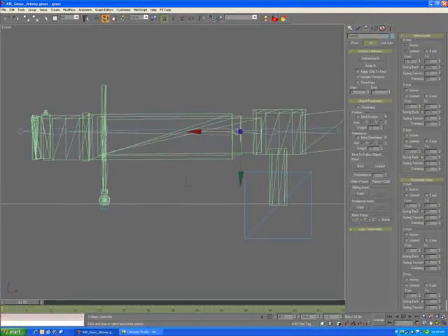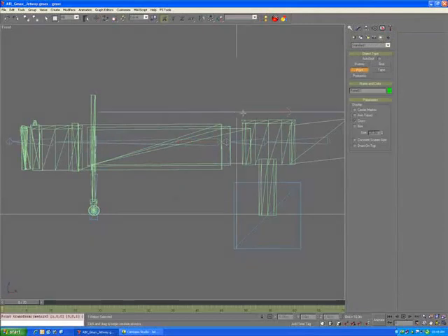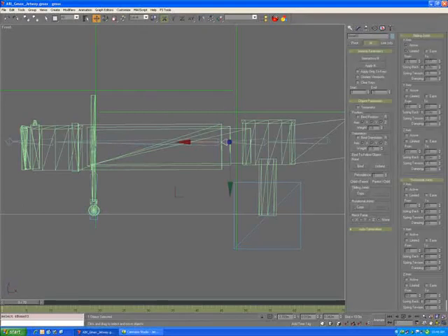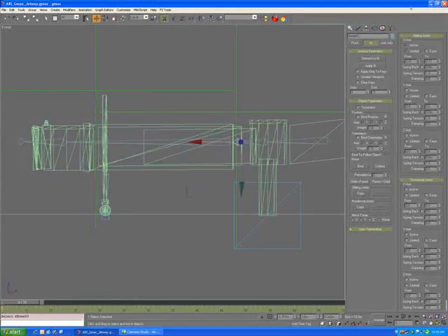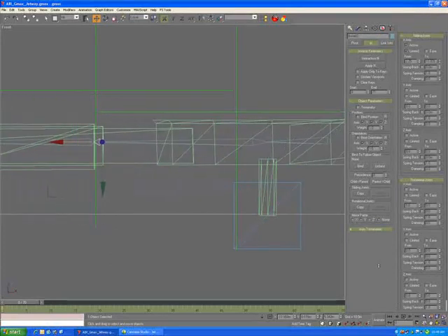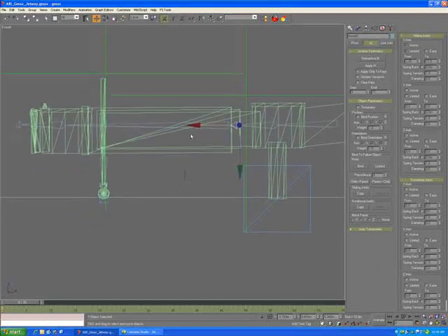So what you can do, if you want to, is put markers in. If we go in here, we can put a point in, say, there. That's the farthest, and then a point in, say, here. That's the farthest that it should go. And then this will allow you to have a somewhat of a guess of what's going to happen here. So we're going to go from that point to the second, and we go all the way out to roughly that point, give or take. And there you go. So now you have that sliding joint set.